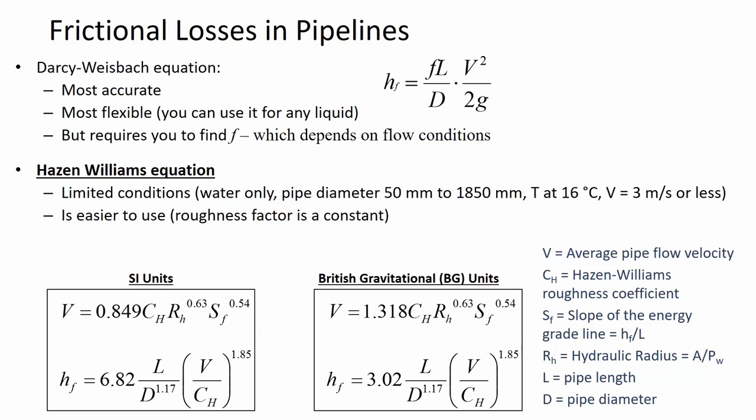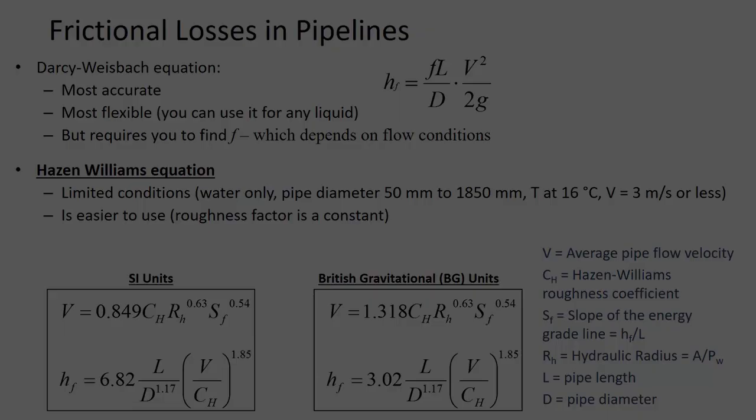Now, your previous experience using the Hazen-Williams equation was in the lab on the pipe rack, right? Each one of those pipes was smaller than 50 millimeters in diameter. So some of the trouble you had in comparing observed behavior to expected behavior based on the predictions was just that the pipes were too small to be accurately modeled with the Hazen-Williams equation. Whereas the Darcy-Weisbach equation isn't at all troubled by smaller pipes or a specific flow velocity or a specific temperature. It's a little bit more flexible.